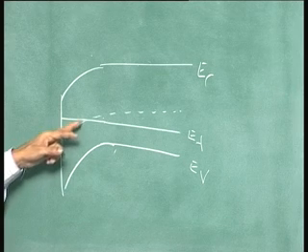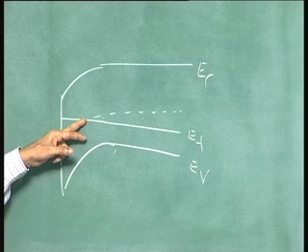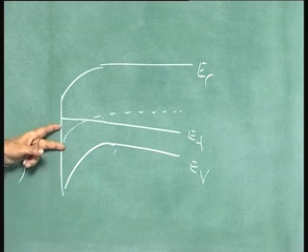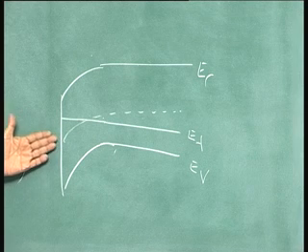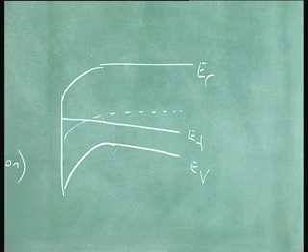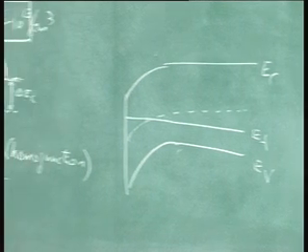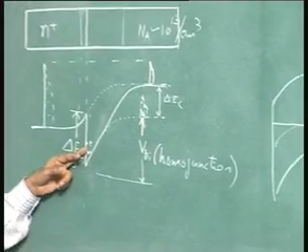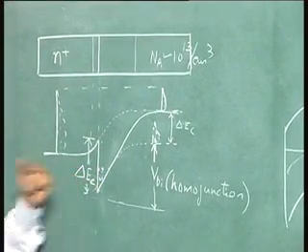If it were just bending up to the intrinsic point, the electron concentration would not have been much in the regular junction, but here it is bending more than that by an amount equal to delta EC, that is what we are telling. There will be electrons and concentration here. In the regular PN junction, even if bending is more, they will not be collected, whereas if you go down here, that notch will contain those electrons, because of the extra band bending.